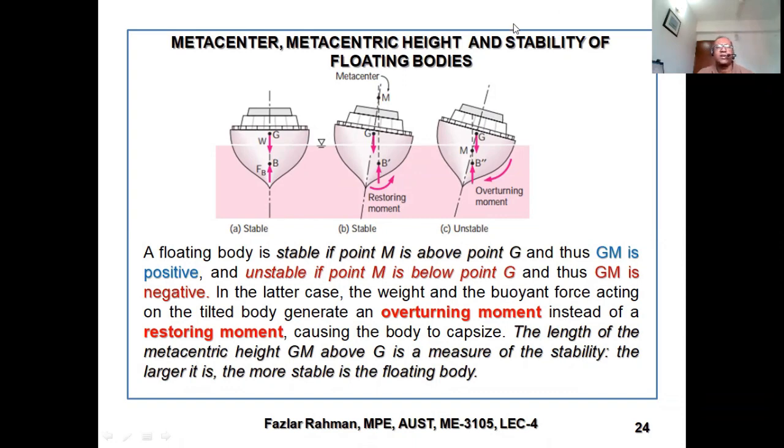Now, how does the airplane work? If you look at the front section of the aircraft, say looking at the front, this is your aircraft wing on both sides. I'm sorry, this will be like that. When it flies, the pressure at the wing works in the upward direction. So the resultant force should work along this direction. Now if you keep the CG over here, or on the left side, then you travel. So try to keep the CG on the same line of action as the upward force coming from the pressure at the bottom of the wing. So that is the application.